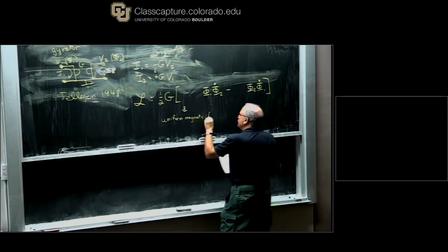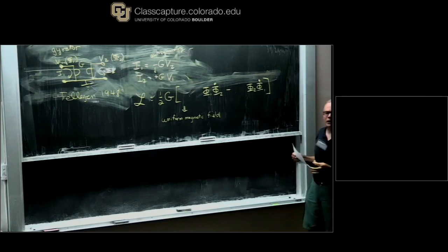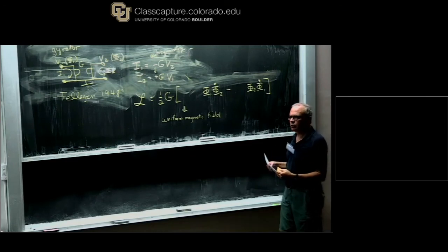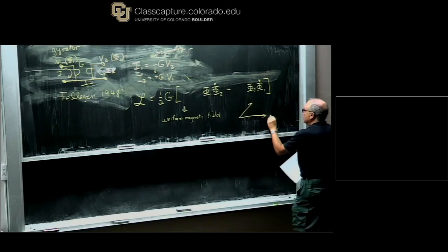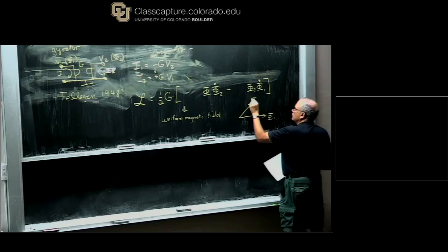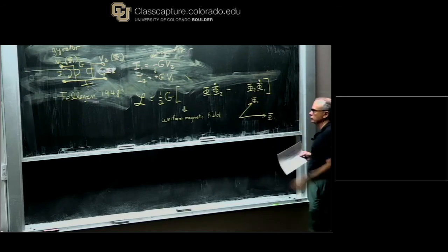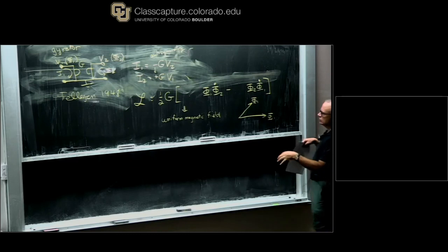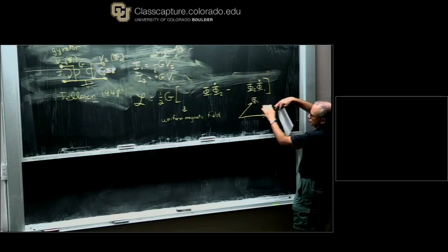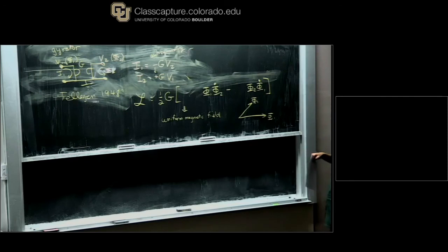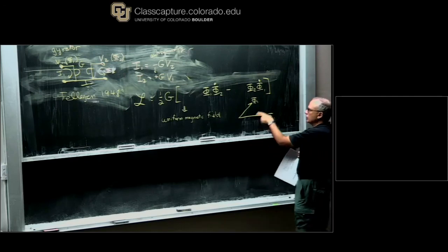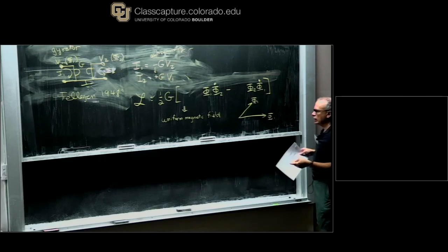Now this is again contributing further to our confusion of effective magnetic field and this and that. What I mean by this, to be more precise, is the following: I have at least 2 variables in my dynamics, Phi1, Phi2. I might have Phi3, Phi4, whatever. And we've seen that inductors and Josephson junctions serve to produce potential energies, say 2-dimensional in this case, and capacitances are just ordinary kinetic energies.